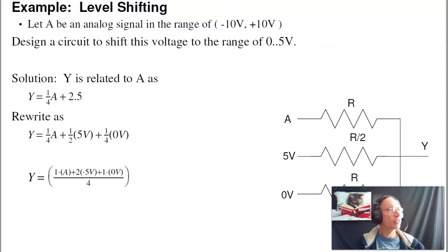So that's lecture number 12 for EE206, Circuits 1, Superposition. If you have 3 different inputs, I can treat that as 3 separate problems. That's somewhat useful at DC. It'll be really, really useful when we get to AC analysis. So we're going to see superposition again. But the idea is if you have 3 inputs, you can treat that as 3 separate problems. That's a perfectly valid way to analyze the circuit. Lecture 12 for EE206, Circuits 1.